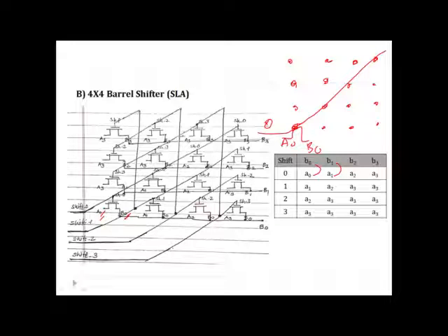So I'll go in the upward direction. I have already drawn an NMOS. I'll write A1 input, B1 output, because these are outputs, right? Now this is the next in the upward direction along the diagonal. So here the input is A2 and output is B2. This is the transistor I'm talking about. So I am done with these 1, 2, 3. Then the fourth one is this, where A3 is input and B3 output. So here you have A3 input and B3 output. So I am done with the shift 0 operation.